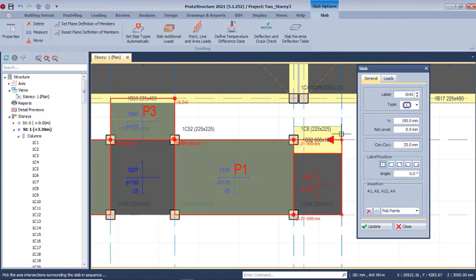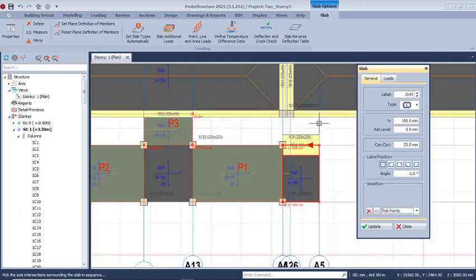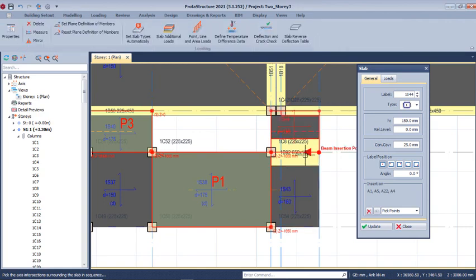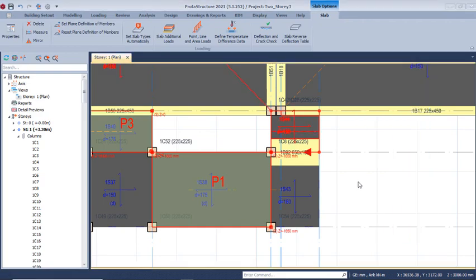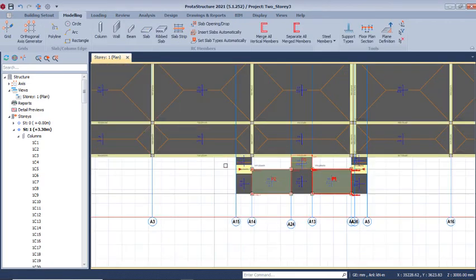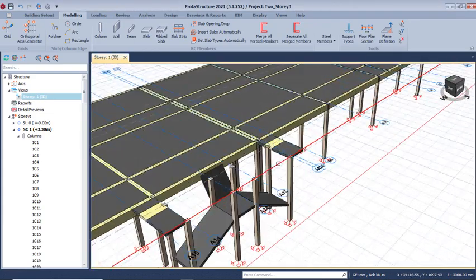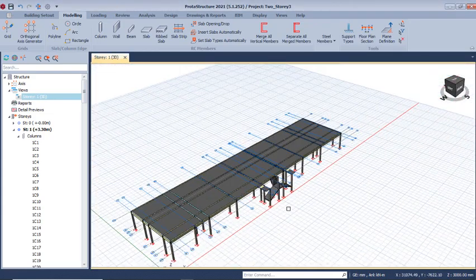The same thing is applicable here. You have to clear the point you picked first, clear it, and then you pick a new point. So we'll have here the first point, second point, third point, and then the first point to have this slab placed just like this. So let's look at this in 3D. All right, right click and then click on the 3D right there. So you will have something of this kind. Now we want to be generating stories.